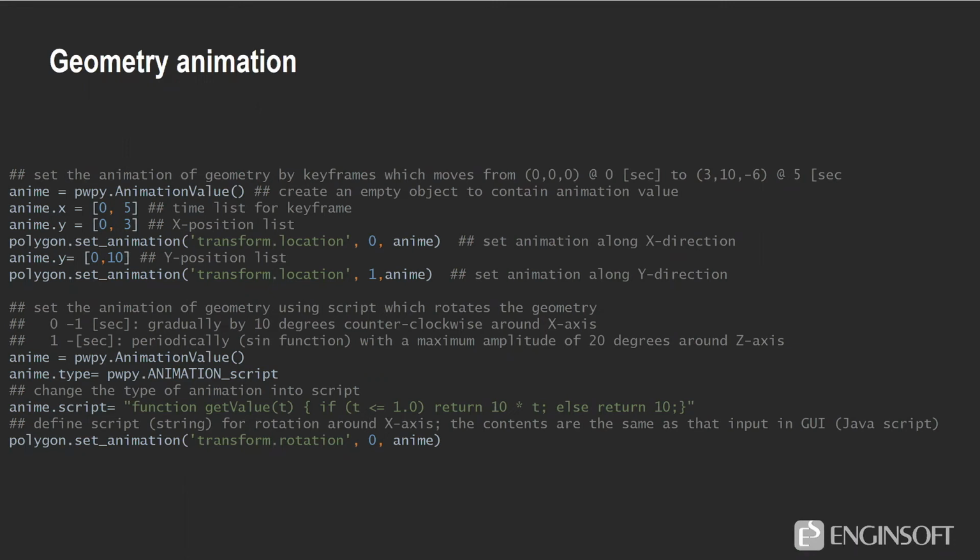modeFRONTIER is an optimizer, and you can automate the launch and the post-processing with the Python interface to test, for instance, different inflow locations for lubrication purposes. Let's say you have a gear and you have an inflow close to the gear. You want to test 100 positions of the inflow. You can do some machine learning or some optimization thanks to the optimizer, modeFRONTIER in this case, and the automation you enable with the Python. Okay. Great.